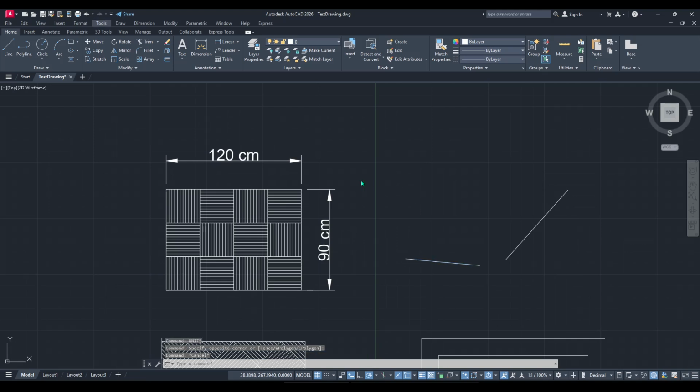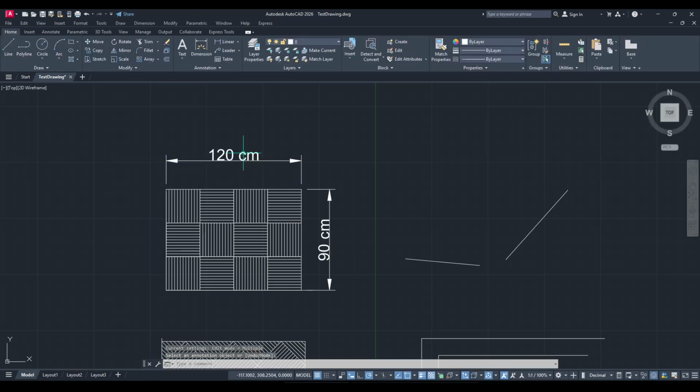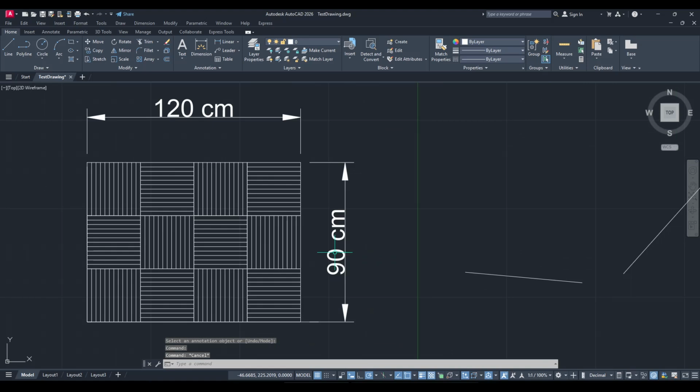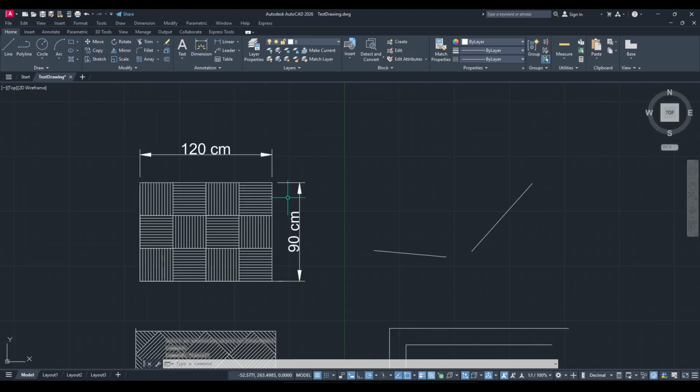There's an important detail to understand here. Changing the insertion scale to meters does not automatically convert or resize any geometry that already exists in the file. It doesn't stretch lines, update blocks, or change dimension sizes that are already placed. Think of this as telling AutoCAD what unit system the drawing uses going forward, not a retroactive conversion tool.